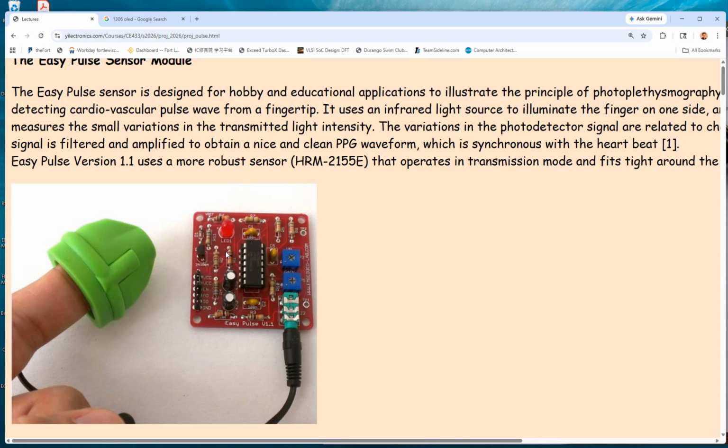Why is 3.3 volts still needed? Since our core, the CPU and all the logic, is running at 1 volt, why do we still need 3.3 volts? It's a really common power supply, right? And it's giving you a good range. Sometimes your analog signal is swinging around 0 to 1, 0 to 1.5, and you don't want to directly use 1 volt, which gives you very little space for other things.